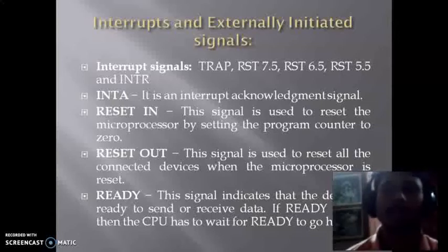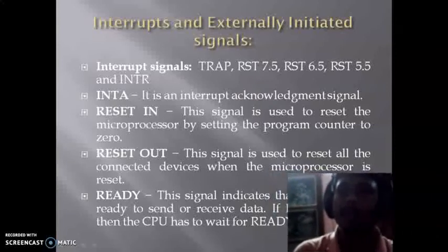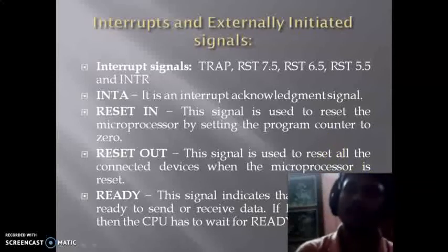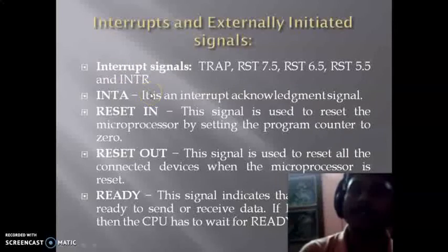At this time the microprocessor may send an acknowledgement to the peripheral device, telling it that it accepted the request. This means an urgent work is being performed by the peripheral device, and access to the microprocessor can be done by pausing the current operations, and the acknowledgement is done through the INTA signal.